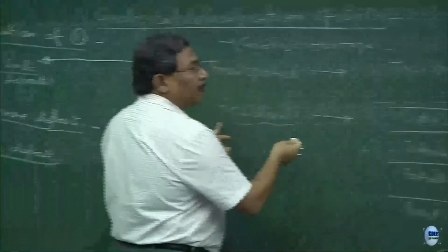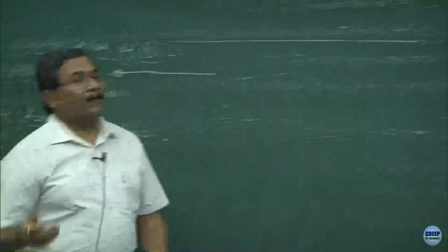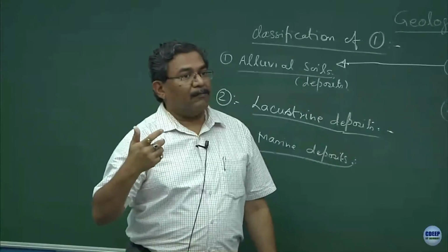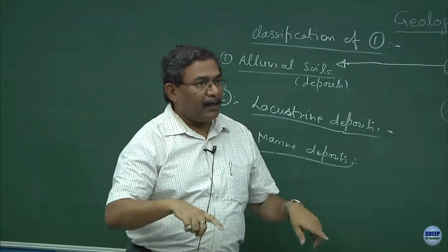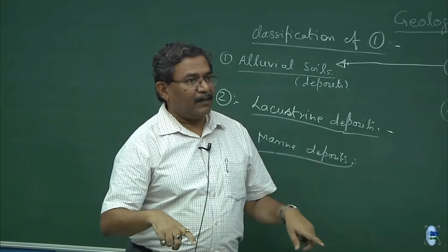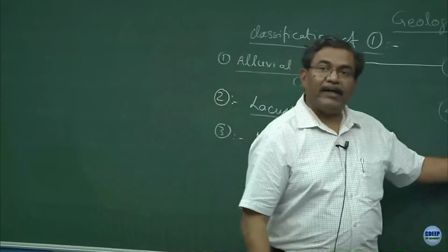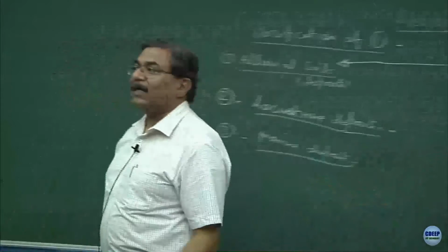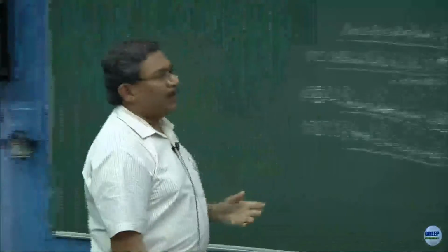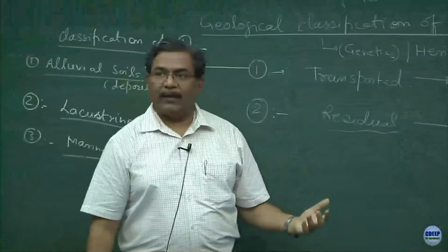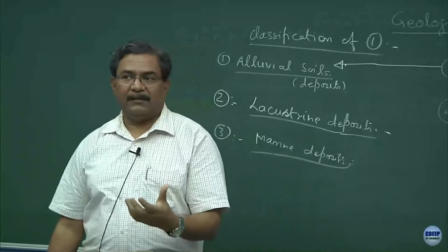Those of you who will be taking a course in offshore engineering will realize this very soon, that these residual soils are the ones which got created because of the weathering of the granite or basalt, clear, and they remain there. They had a lot of organic matter in them, they got disintegrated because of bacterial activity, and they got converted into clays. Clays are another variety of soils, what you were referring to as mud or slush. Slush and mud are not technical words, clear. So, we have introduced two words today, one is sands, another one clays, fine.